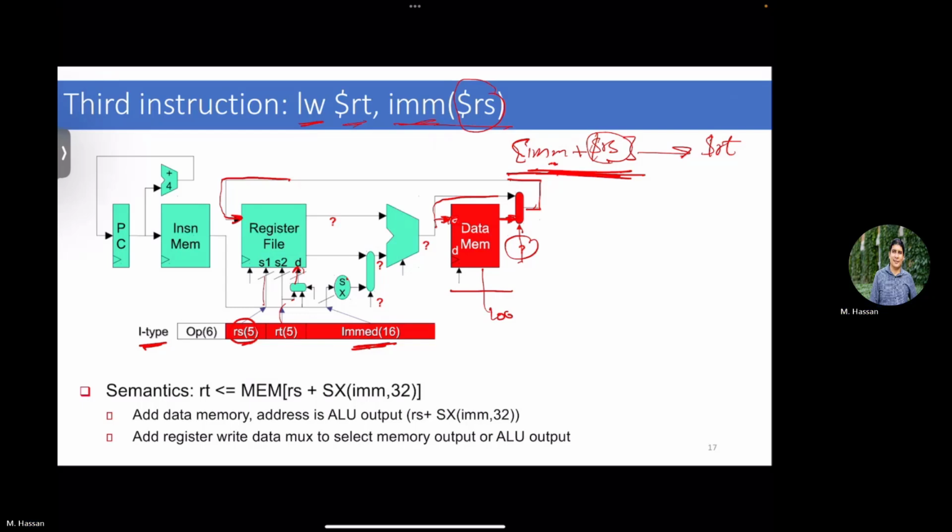Any other question? Yeah. So right now, all the muxes are being driven by the opcode. Is each of the muxes driven by one bit in the opcode, or how does that work? Yeah, I guess you are referring to the selection lines, right? Most of the selection lines will depend on what instruction I'm executing. So in the control, yeah, exactly. The control is the one that feeds all these selection lines and all the enables. But then is the opcode limited to only having 6 muxes, or can't that be the case?